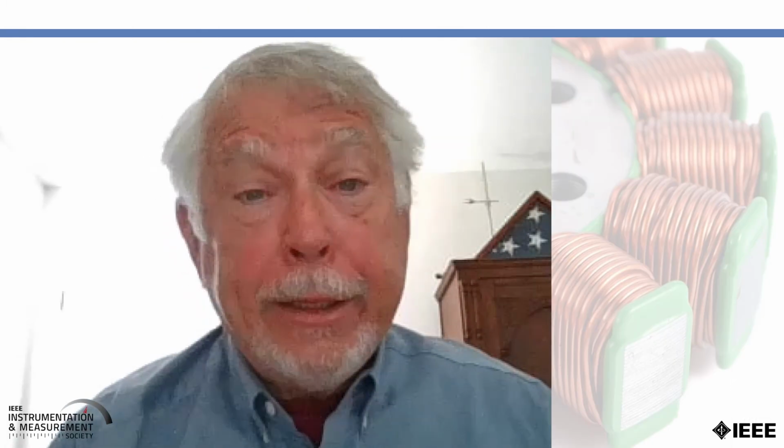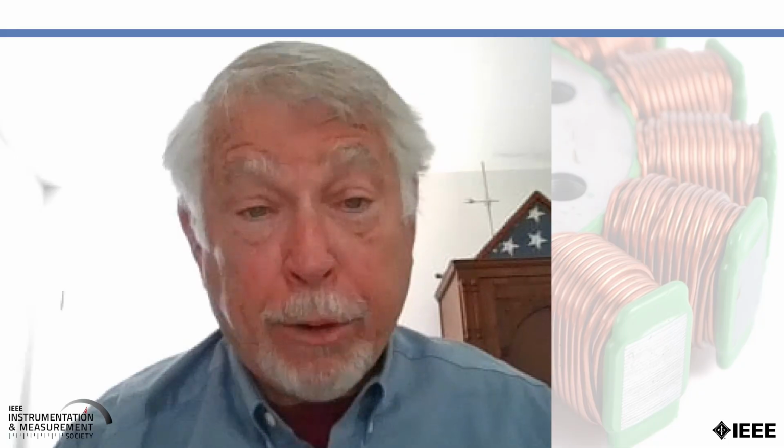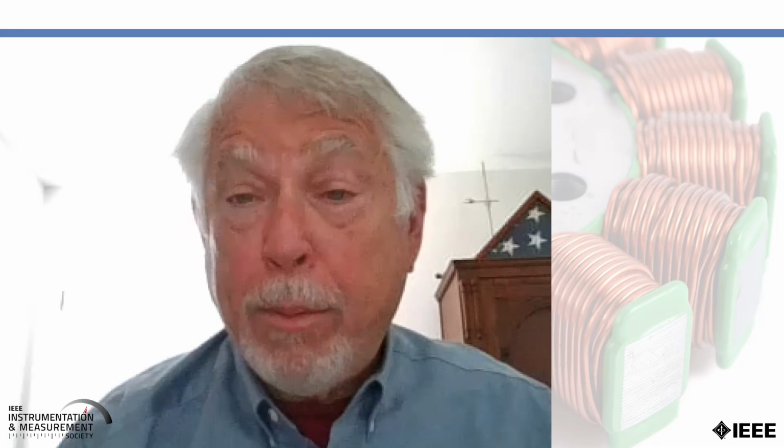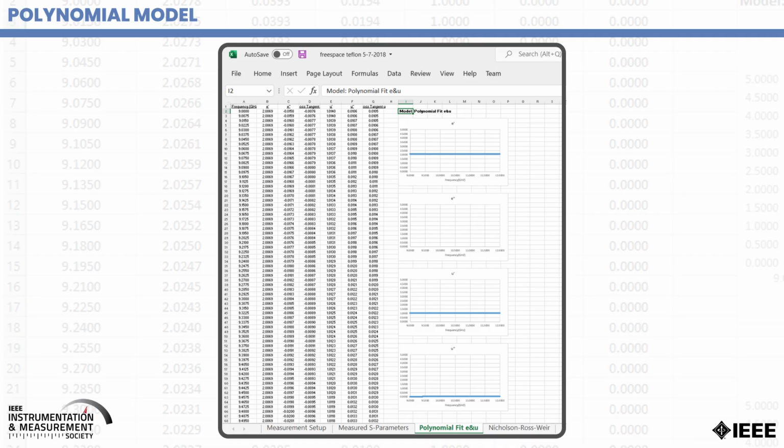Here we calculate the same measurement using the polynomial model, and we're assuming here in the polynomial model that it possibly may be magnetic. And as you can see, we get essentially the same values that we had gotten before, but the magnetic property is essentially 1 plus j0, so it probably is not a magnetic material.